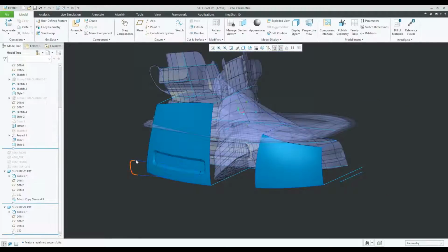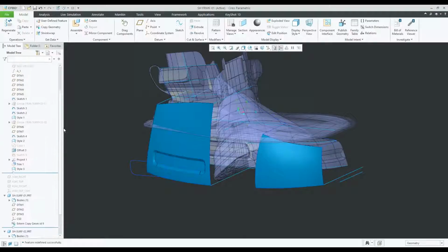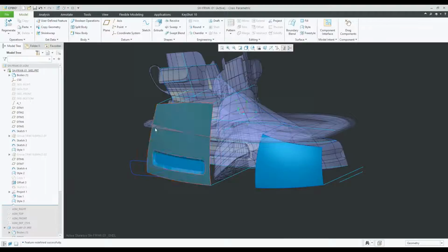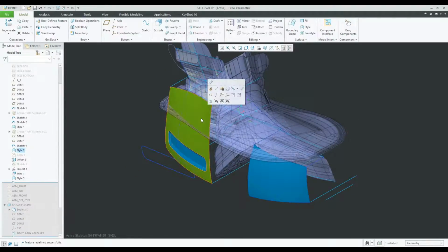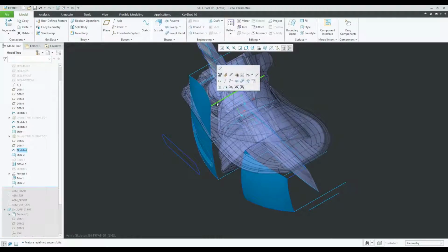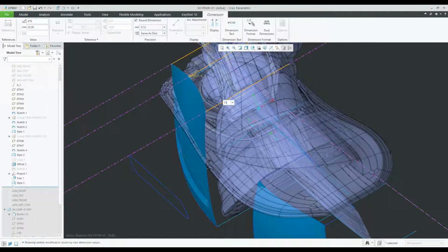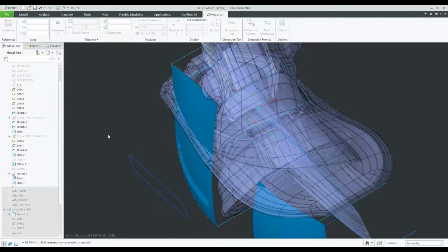So just to show that, for example, if I go into that skeleton component, and I take this surface and style tool, and let's use that framework that we have. So let's grab sketch 4. Let's edit this dimension. Let's take that back to 15, for example. Regenerate, right?